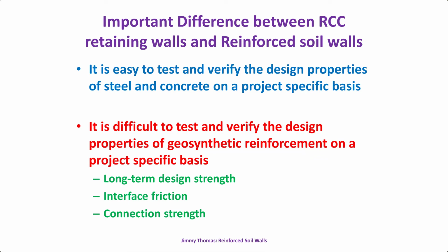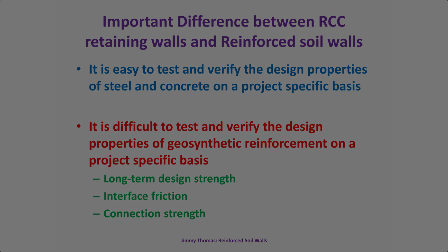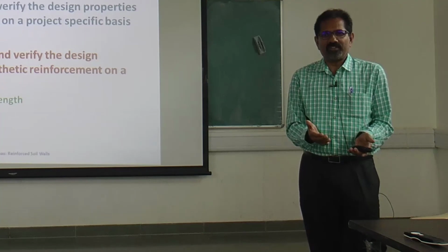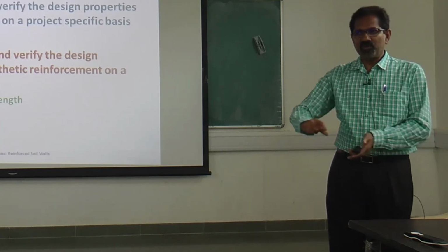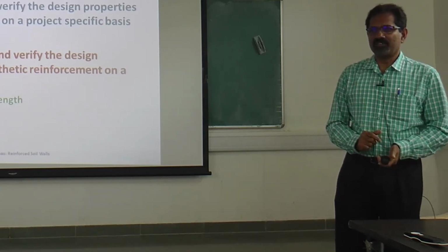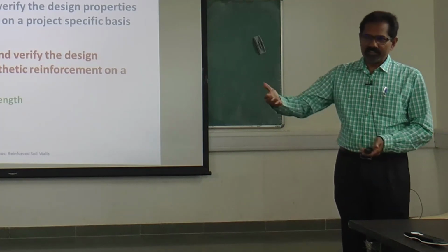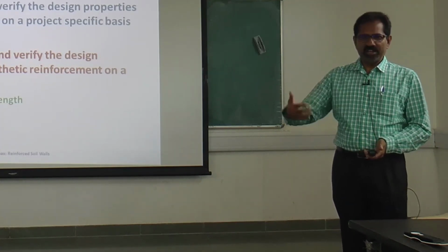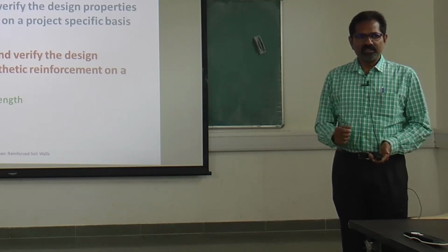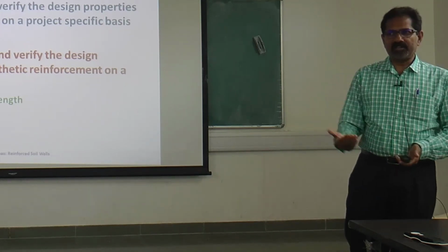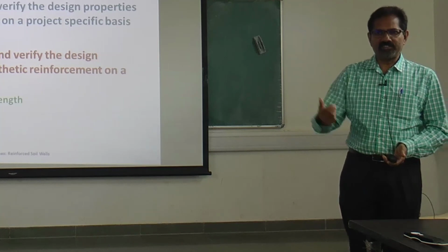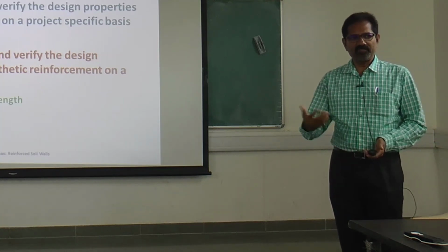Similarly for interface friction and connection strength. Suppose I'm a designer and I have a project. If I say I want to do all these tests, that's not possible. These are all very time consuming, expensive tests. So we have to take this data from the manufacturer. We have to rely on the data, so we have to verify. For that also, there is third-party testing. We have to look at the laboratory which has given the results. Then there are certifications. That's very important.